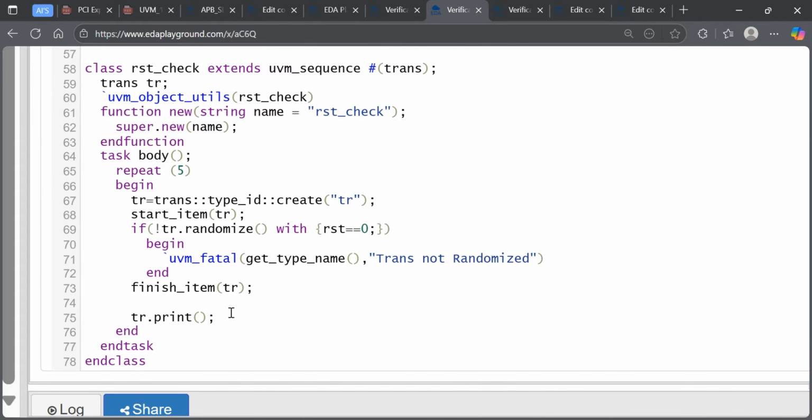Now this is our second sequence. The second sequence we have written for the reset check. Here you can see your reset is 0. Reset is 0 means whatever the input of JK is, we don't have to worry, because the output is always 0 since we have used reset equal to 0. Our reset is working on the negate only, so we are not focused much on the JK. Here we are checking the reset.